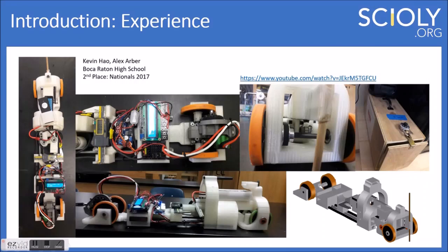We attached the main caliper portion, this tooth here, to a 3D printed part. We epoxied that in, so that was very solid, very rigid. This was our first linkage here, and then we had this arm that connected the first linkage to the second linkage, and then the third linkage here. You can see the ball bearings there, so those were free to rotate. This third linkage arm was directly connected to the front axle. That is how we controlled changing the angle that the front wheels started at, because obviously we need to change the curve based on the distance. I'll talk a little bit more about that later as well.